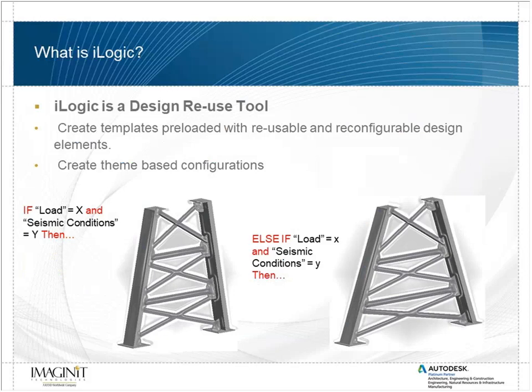So it takes into account the parameters that you've entered in there for load and seismic conditions and does something else. Now, if you change that, then it knows what to do because the engineering is built into the model and it behaves accordingly. So you really don't have to make decisions that are part of your proprietary understanding or your tribal knowledge of these models. Those decisions can be built into your models, built into your assemblies.